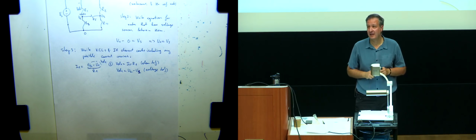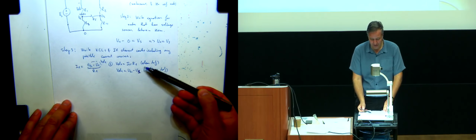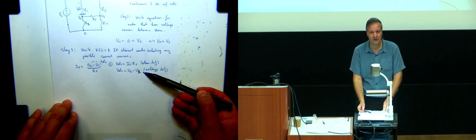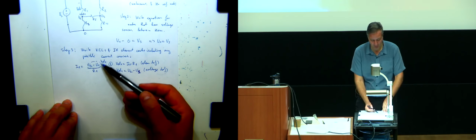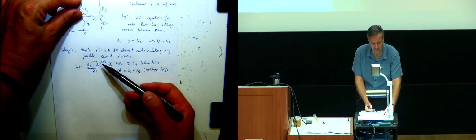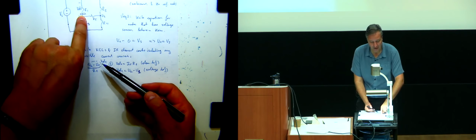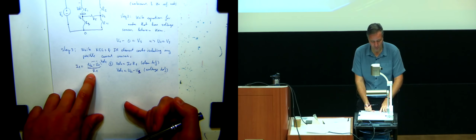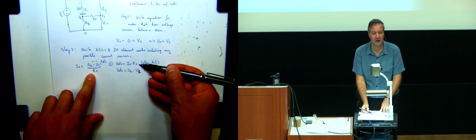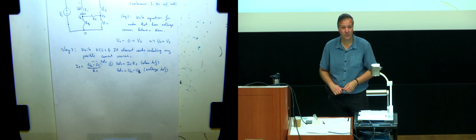Questions? All we did is we used these element definition and voltage definition, right? So V element 1 is U2 minus U1. That's the voltage across here. And we're calculating I1 as voltage over R1. For that, we're using this element definition here, Ohm's law. Does that make sense?